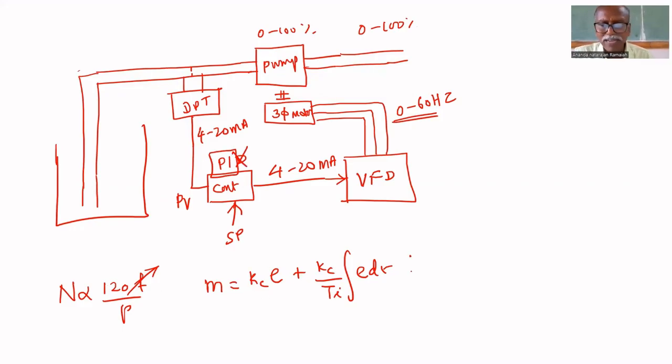That's why this plus bias. Always bias is required. Already we have discussed why bias is required. Suppose the car is running at 60 kilometers per hour. Are you giving any input, or because of zero error, you are not giving any input? You must give some input to run at 60 kilometers per hour. The same meaning here. If there is no error, at that time it should give something to get the required output. For that, that bias is required. Controller will not find the bias. We have to find the bias. That bias the controller will add and it will give.